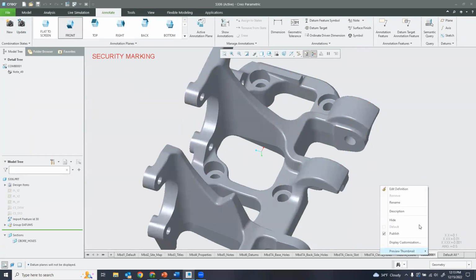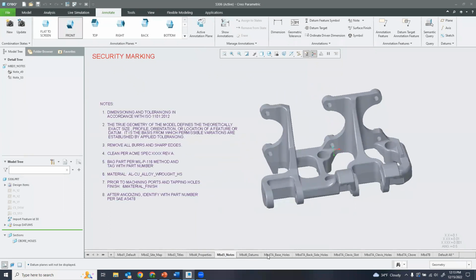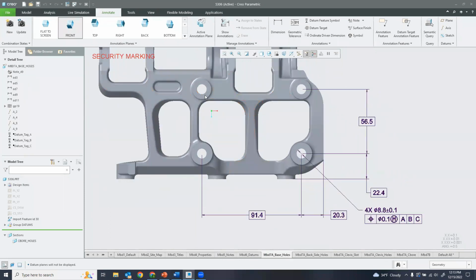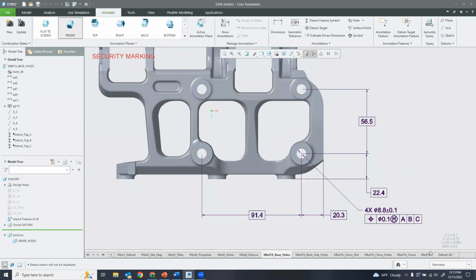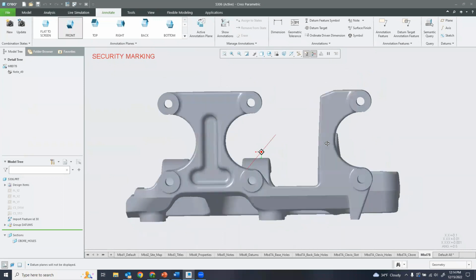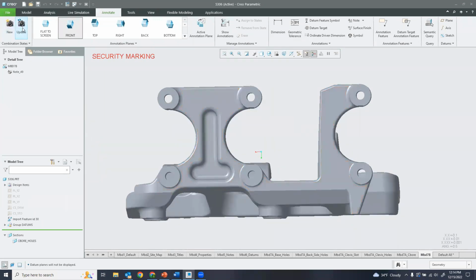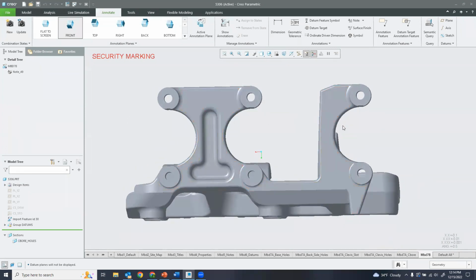I'll go ahead and drag that over and rename it to MBD 7B, for example. Now notice when I click through these combination states, it saves the orientation. Even if I spin this around and come back to it, it's going to maintain that same orientation. Now to do that, let's say we want a specific orientation, something like this. All we have to do is click on this update button. And now if we spin it around, maybe exit and come back, it's going to maintain that same orientation.